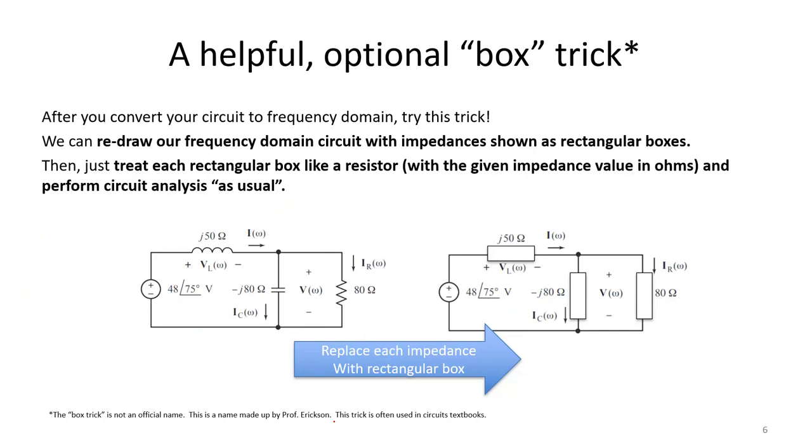Before we move on, let's cover a few more helpful tricks as we solve more AC circuits. In our previous video, you'll remember I introduced this box trick. This is not an official name, this is just something silly I made up. But often it's very helpful to use this trick after you have converted your circuit to frequency domain. Remember, in the box trick, all we're doing is we redraw our inductors, capacitors, and resistors as boxes in frequency domain.